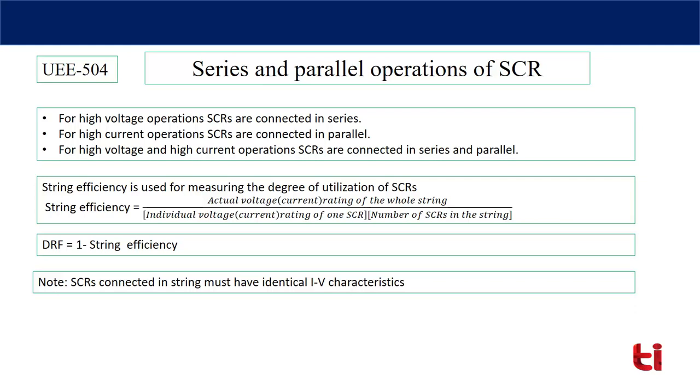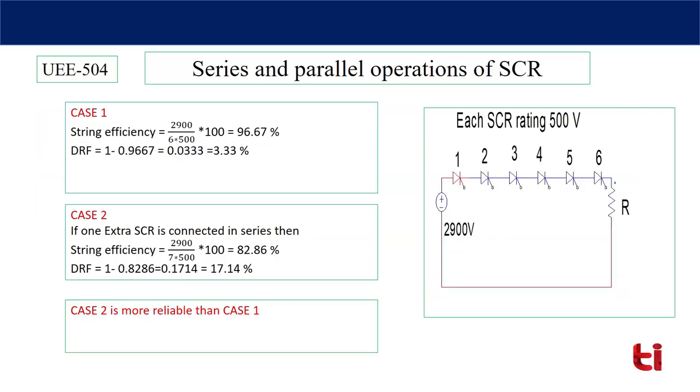SCRs connected in a string must have identical IV characteristics. This is impossible to achieve, because two SCRs of the same rating and same specifications don't have similar IV characteristics. This we will discuss in detail. Let's see.